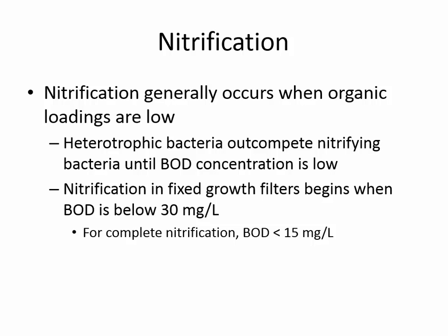Nitrification is more difficult to achieve in a trickling filter because denitrification, remember, is an anaerobic process. There has to be a lack of oxygen to have the conversion of nitrate into nitrogen gas. So it's a little bit more difficult to have that, except that the outside of the slime layer is aerobic, and the inside of the slime layer can be anaerobic.